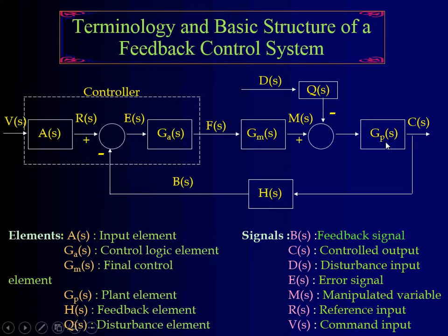In other words, this is you going to that setting, setting the temperature you want, or having the vehicle adjust to the specific speed that you have set. Okay. So after you do the measurement, that measurement signal goes through the so-called feedback element, which could be, for example, a box that transforms the RPM that you measure from a motor into a voltage.